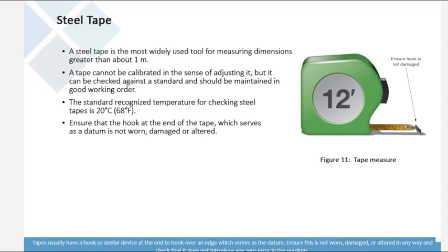Tapes usually have a hook or similar device at the end to hook over an edge which serves as the datum. Ensure this is not worn, damaged, or altered in any way and check that it does not introduce any zero error in the readings.